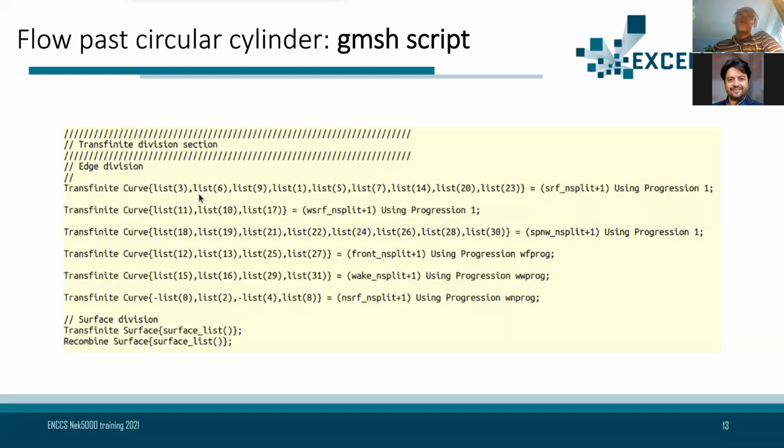After splitting all the lines, I can start to split all the surfaces, but this is not automatic meshing inside Gmsh. That's what you have to understand. To get a hex split, I do this manually, and that's a drawback.